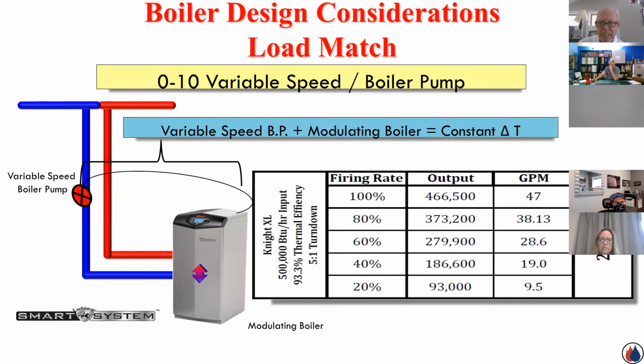So a solution might be to take that ECM technology and attach the signal from the boiler, which is watching its inlet and outlet temperature sensors on the heat exchanger, and change the flow rate to maintain the desired delta T across that boiler. And that leads to a much more efficient boiler plant and a considerable amount of less cycling of the boiler. And again, this is all being connected up here with our primary, secondary Ts.